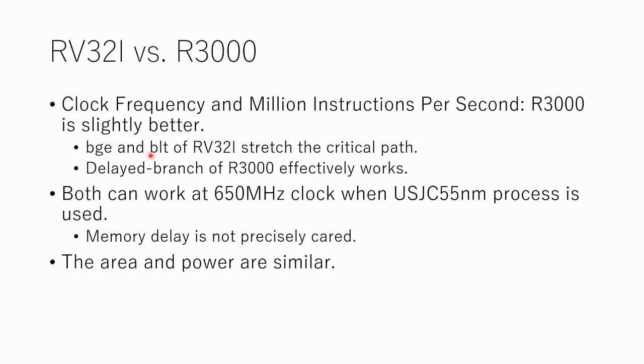Branch greater equal and branch less than of RV32I really stretch the critical path. And the delayed branch provided by R3000 effectively works. My evaluation is based on the students' design of programs. They used delayed branch and they used the branch delay slot. So the performance is slightly improved.